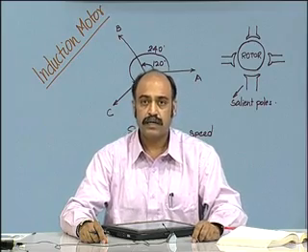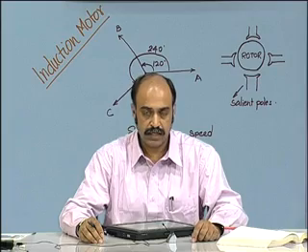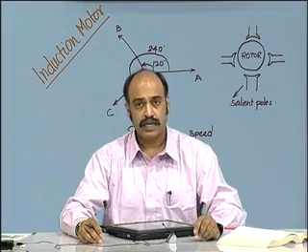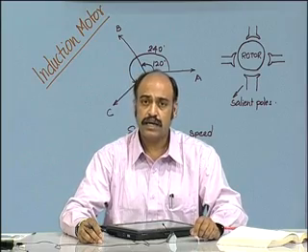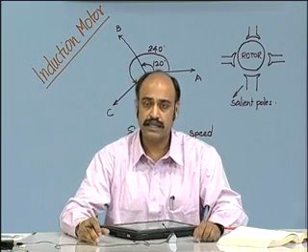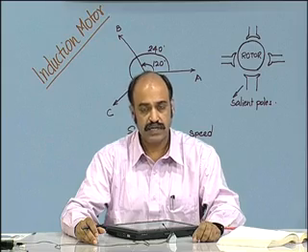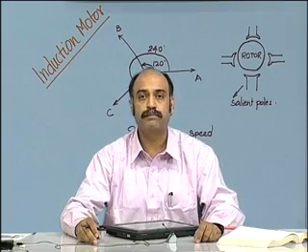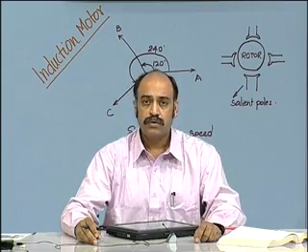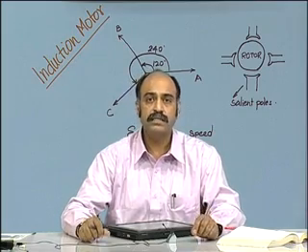Which means that the synchronous frequency is fixed if the number of poles are fixed in the case of the induction motor. So if the synchronous frequency is fixed, then the shaft of the induction motor is going to be less than the synchronous frequency only by the amount of slip. So more or less the induction motor is a reasonably constant speed motor.